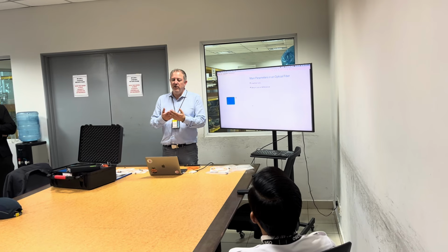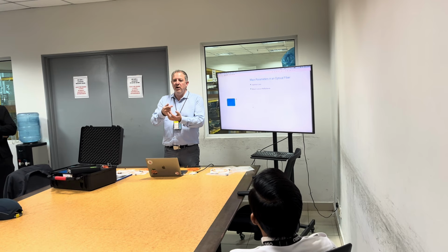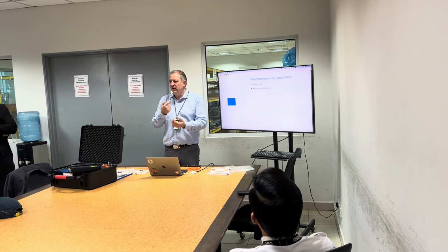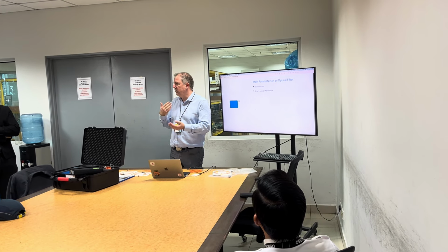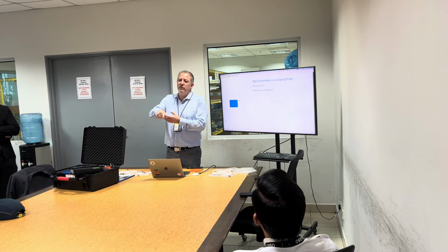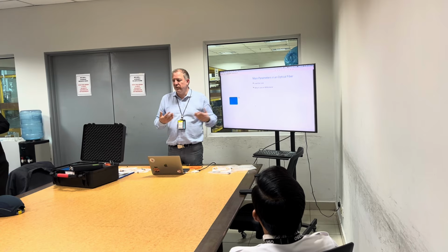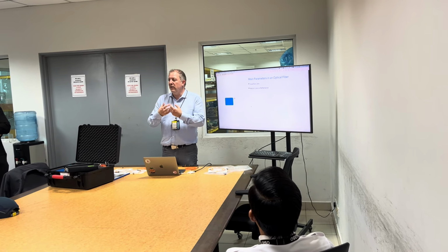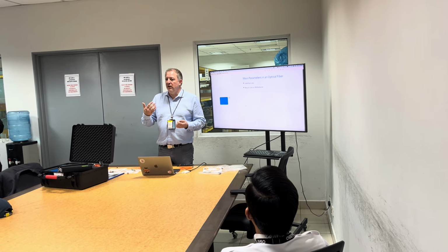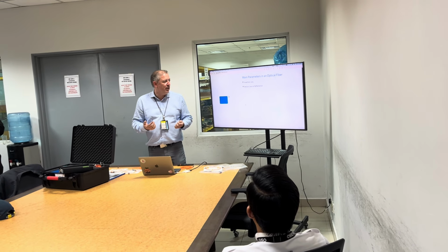That's when you have a connection, the light that's not going to go through, but is going to be reflected. So as I mentioned, if you don't have physical contact, most of the light will be reflected. If you have physical contact, most of the light will go through. So these are the two parameters that are important to qualify the quality of a connection, or to qualify the level of damage you may have on the fiber. Okay.